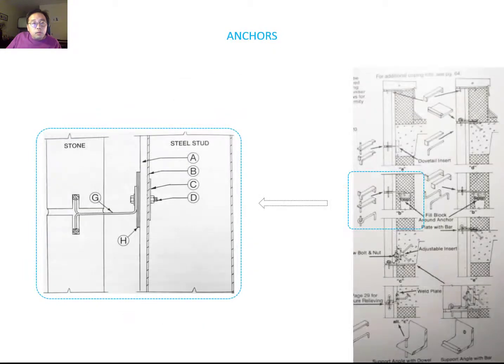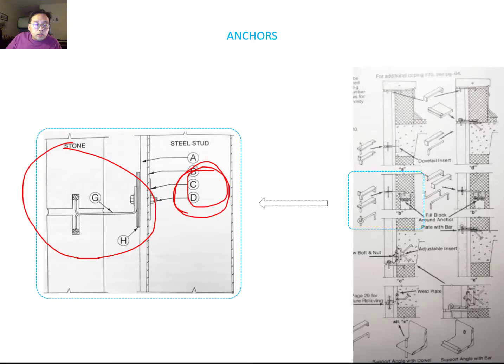But you can also find out what kind of anchoring system you can use. This is a typical anchor accessory. This paneling anchor system is set up in the expansion joint between the two stone panels. So this is the most typical connection in stone stacking. You can see the steel structure, and then they're using the anchor to hold these two stone types.